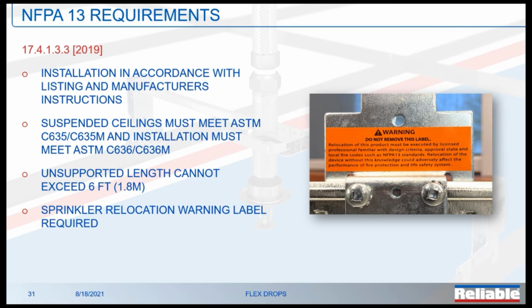So one of the early promises made with this was, wow, when you go do TI work, you can simply hop these over to the next tile and move these around. Well, primarily the AHJ world got a little bit concerned that Mr. Owner might be out there doing that himself. And so this is the attempt to essentially thwart that and say this must be done by a sprinkler contractor.